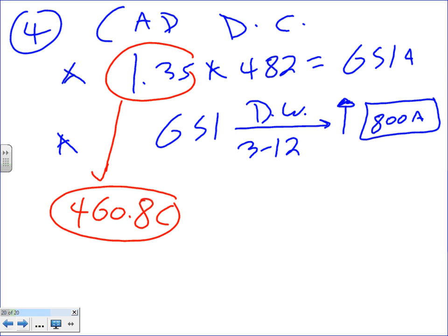Can you guys see where it says 20 kVAR? The full load amp of the 20 kVAR, the size of the wire at 240 is number 4. The fuse is 80. The switch is 100. At 480, the size is 8. The fuse is 40. The disconnect is 60. And at 600, they give you the size.